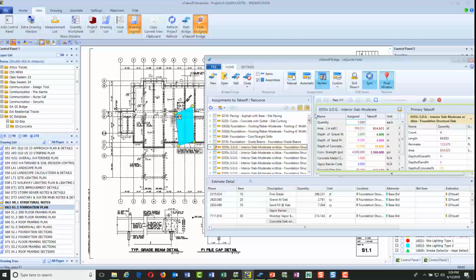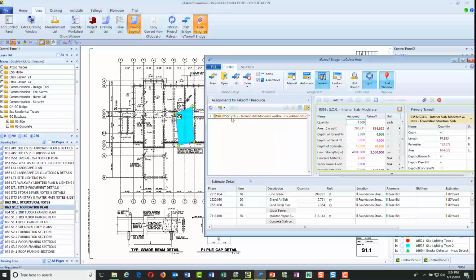You'll notice it's got a pencil mark on it. If I hover over this, it says it's changed. These are the things that haven't changed. So I can click that to filter and say just show me the things that have changed. Here are the changes, by the way, that it made. So here's the area square footage because I increased it. There's the other information that we did, and also you'll notice here that the perimeter changed because I've increased the size. All this was keeping track of, and I have this little flashing box here that says, hey, do you want to apply these?